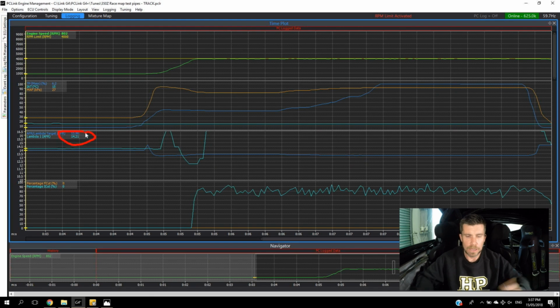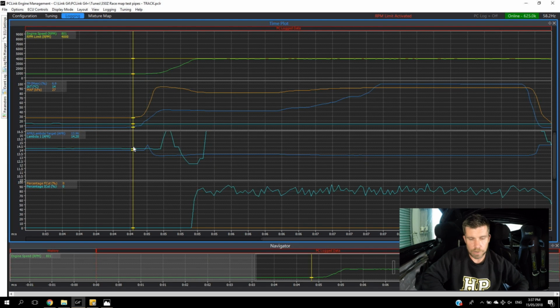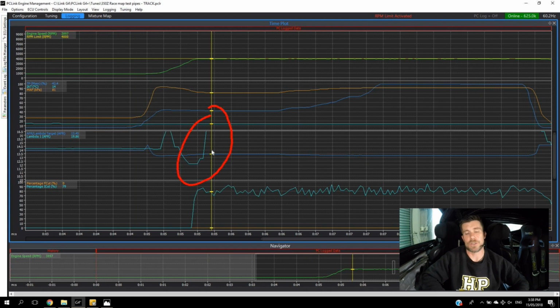and it's the oxygen that the lambda sensor or wideband sensor is detecting and measuring. So we can see here that prior to our test we're sitting right on our target or pretty close to our target, and as we go through onto full throttle, we can see that our air fuel ratio disappears off the top of our graph lean. In fact, it's sitting at about 19.8 to 1. So this isn't indicative of a problem. This just simply means that there's a lot of unburned oxygen and fuel going past the sensor and it's detecting lean. So just an important aspect to understand there.